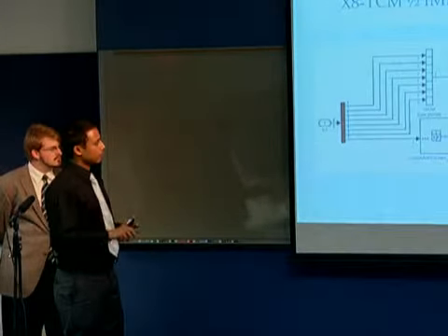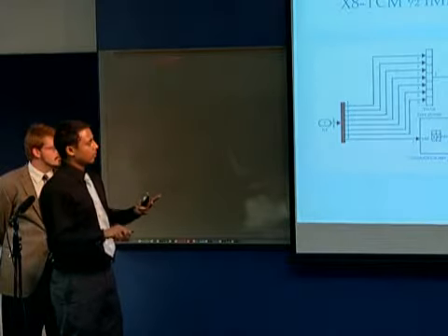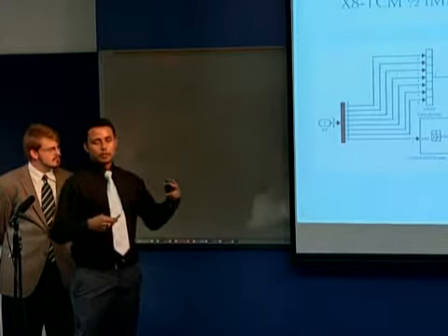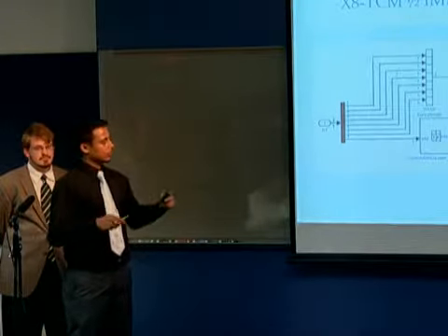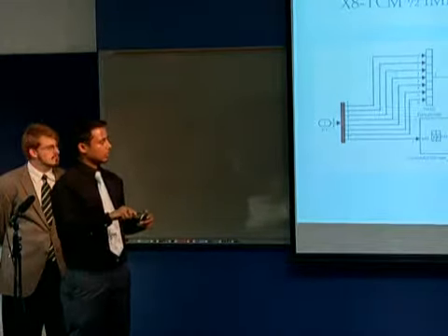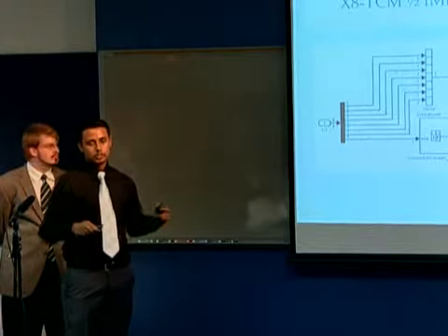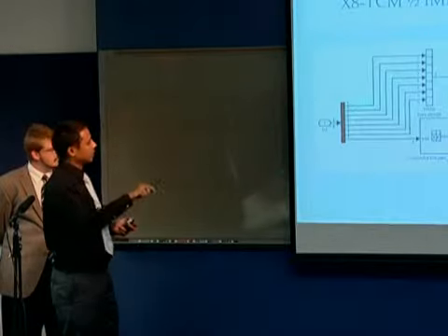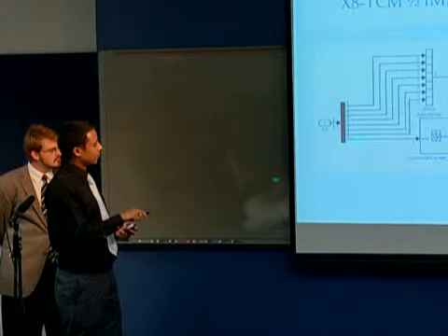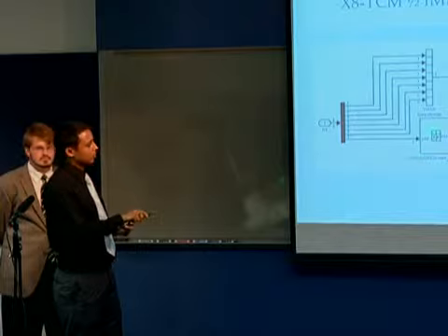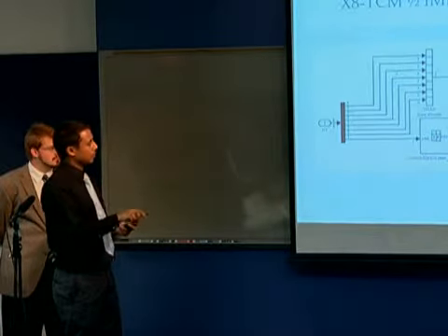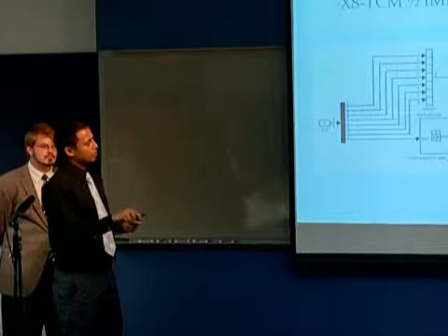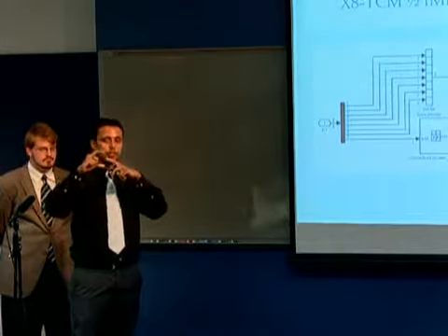Here you cannot see 2 bits coming out, but this is 128 by 8, so that means it's a subset. This convolution encoder is outputting a subset W, X, Y, or Z. Each is of size 128 by 8. One bit, the last bit, goes into the convolution encoder and outputs a subset, and the remaining 7 bits choose which coordinate in each subset to transmit.